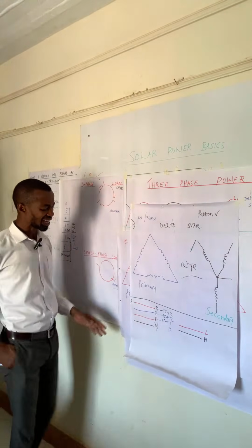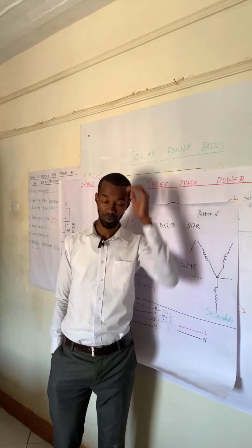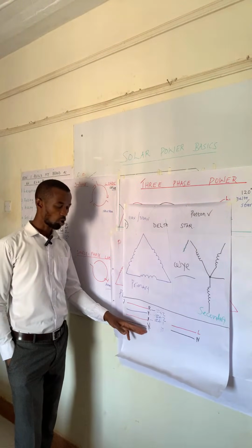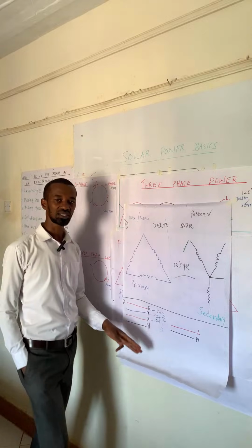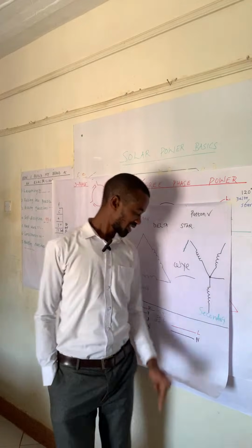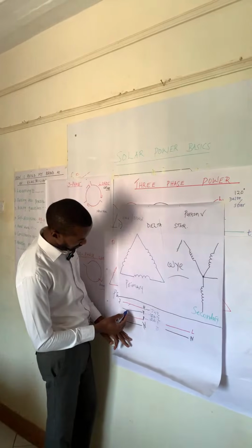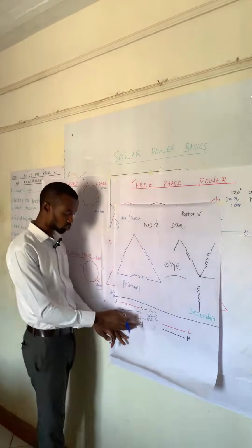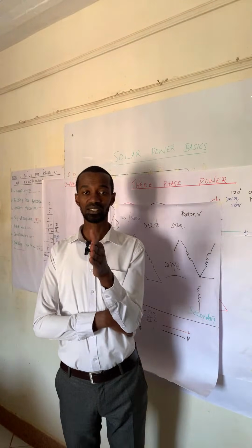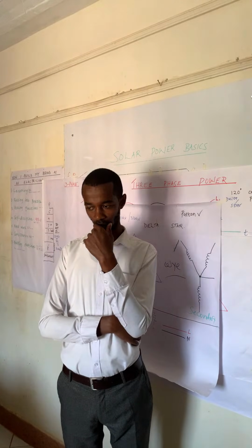All right. There are other cases whereby you find that in a commercial apartment or commercial setup, we have what we refer to as pumps, or a lift, which uses a motor. This motor is a 3-phase motor. Now, what the technician will do in that case is to tap from all of these phases. The neutral in that case will not be required, because remember, when it comes to 3-phase machines, 3-phase motors, you don't require a neutral.